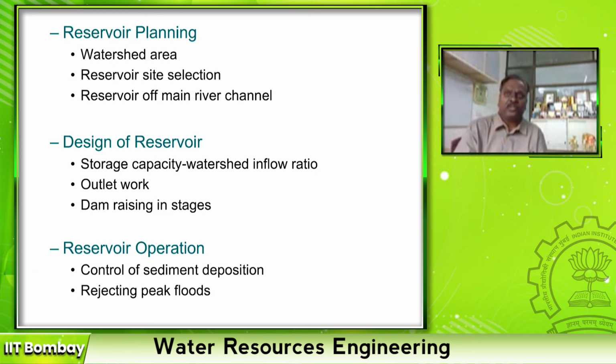Earlier, the surplus water used to go above the dam. Nowadays, people are designing the orifice spillway. That means the flood and sediments get discharged from the bottom of the dam, so the outlet works for a dual purpose: one is flushing the sediment, and the other is releasing the surplus water.